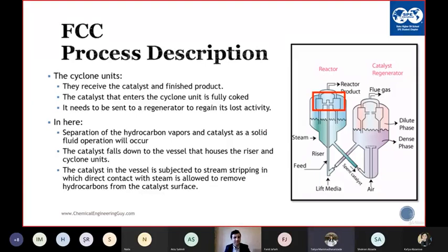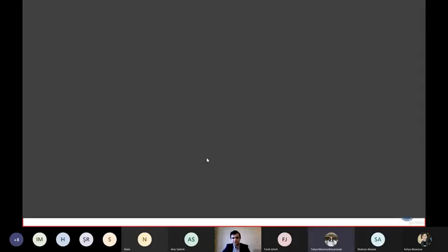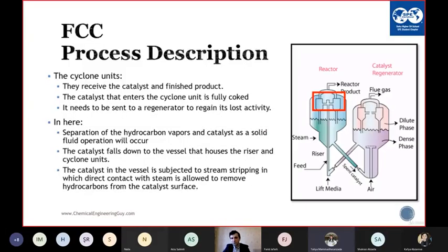Okay. If I don't mistake, they are one type of the separation processes that we use in the process equipment. They are mainly used for the microparticles. I mean, the separation processes are based on the size of the particles. That's why for the micro ones, we use hydrocyclones. Yes, it is correct. Thank you. Okay. So cyclones are used to separate the catalyst microparticles, catalyst particles, from the gases.